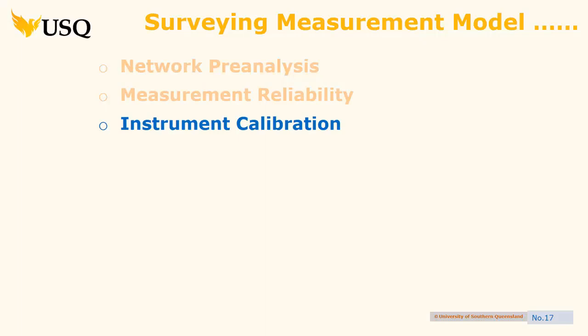Instrument calibration. Hopefully you understand from Module 2 this year that going along and just calibrating your instrument on the government baseline, which is called a Regulation 13, I think, right? Just doing that actually is for cadastral standards. It will give you a report, but you need to actually understand that calibration well enough to go, I'm not setting out blocks of land, I'm going to be testing down to 0.5 millimetre on a bridge. Can my equipment do that, right? So calibration is beyond just going, let's go to a calibration range.